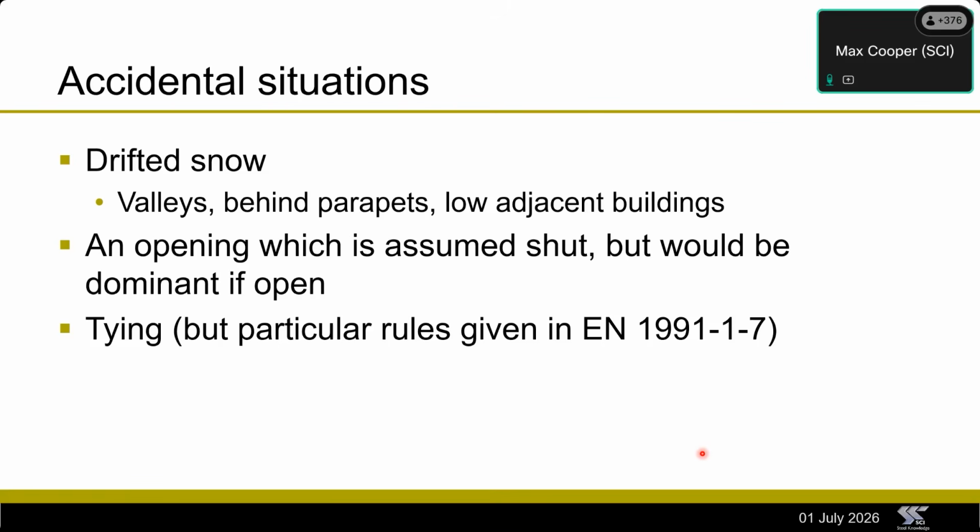But when you come to look at the purlin design or the purlin spacing, these drifted snow load cases, even as accidental combinations with no load factors, can still govern the spacing or the purlin thickness, because you can get quite high concentrated loads. So that's drifted snow.